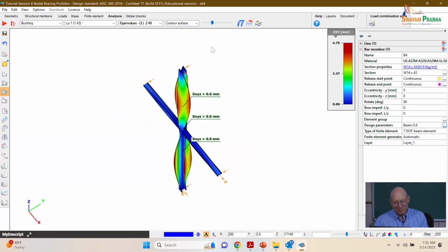If you were really alert, you might have said, wait a minute, I've got a rod brace in the middle of that, I better check torsional buckling where KLZ is 30 feet, like we were talking about earlier. KLY is 15. It turns out that's not the critical buckling mode in this problem.